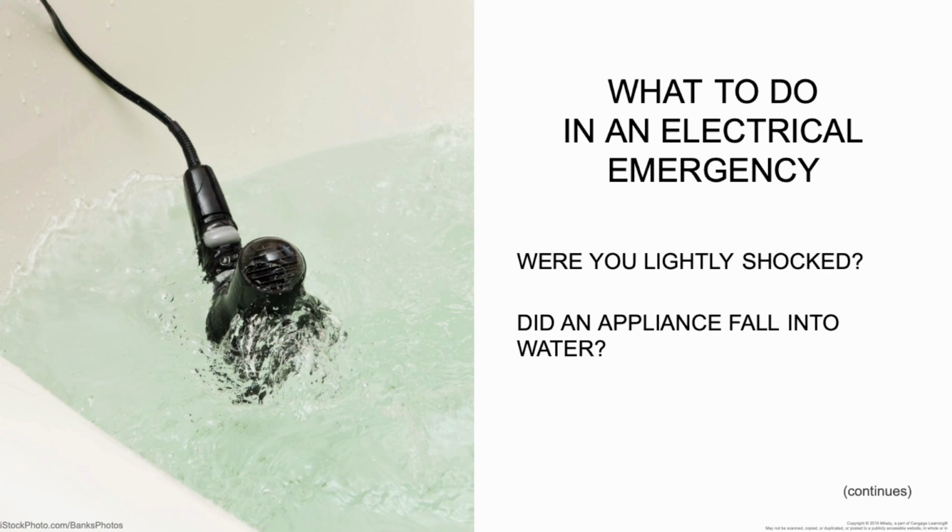Stop using the appliance immediately, turn it off, or if it's on, leave it on and immediately reach out to an electrician. If you can safely unplug it from the wall or turn off the circuit breaker to that outlet, me personally, I would go straight to turning off the circuit breaker. I'm not going to touch that appliance anymore. Replace the appliance or have it repaired by an authorized repair representative. And if similar issues occur with other appliances in the same outlet, discontinue use of the outlet and have it approved by a certified electrician.